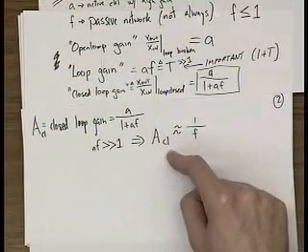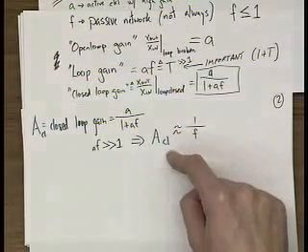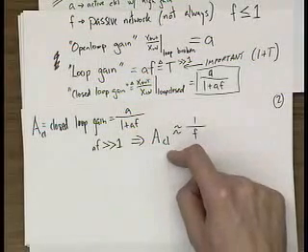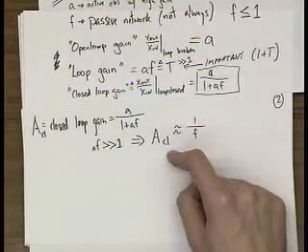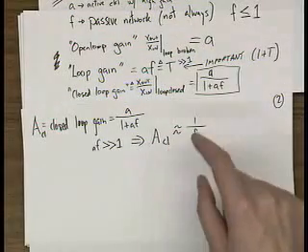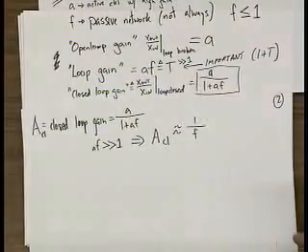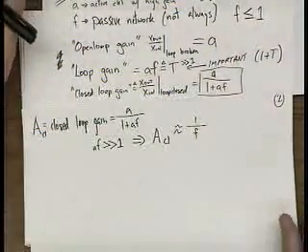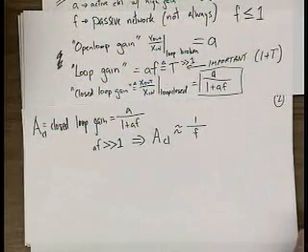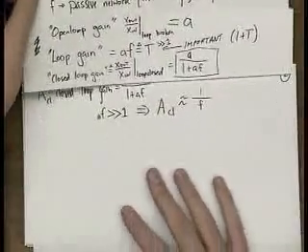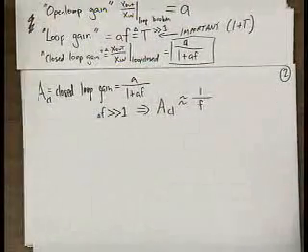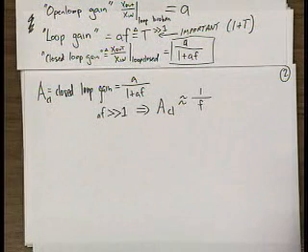If you need a very accurate gain circuit, like if I want you to make a circuit that has precisely a gain of 2, you probably are going to want to use feedback to accomplish that goal. Because, as we'll get to later, the ratios of the feedback networks can be set much more accurately. Okay, so that's the basics of feedback, and the question is, well, so what's all this series shunt, shunt series, and all that other stuff?